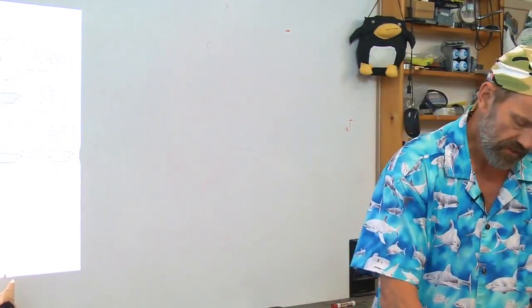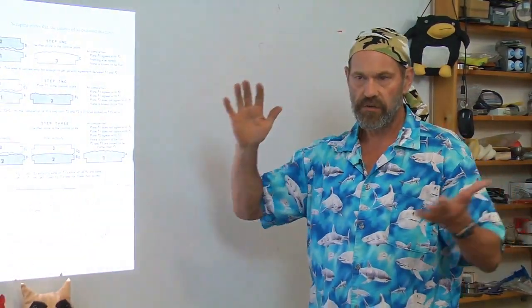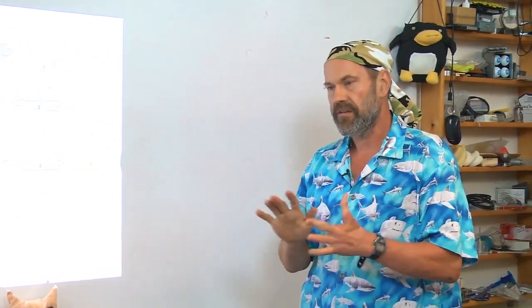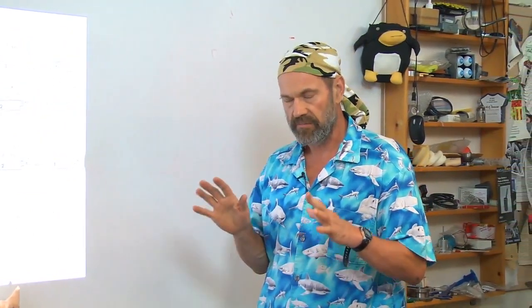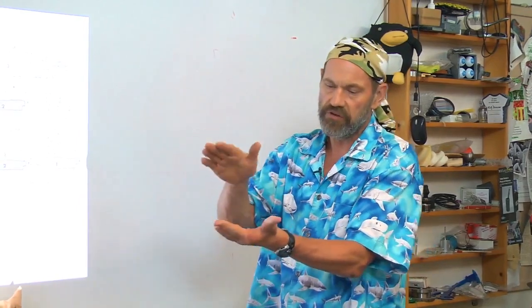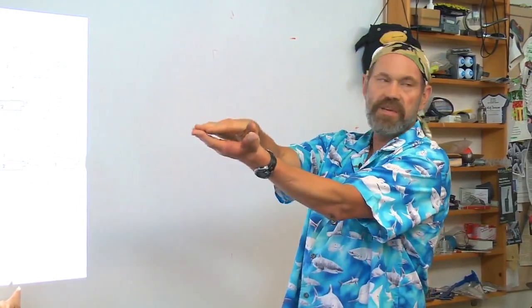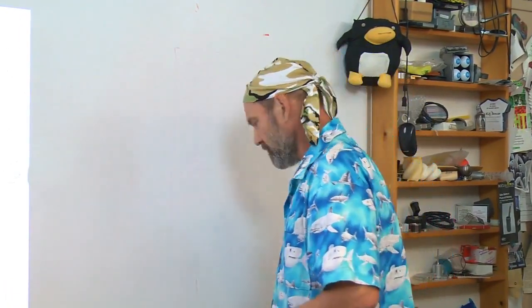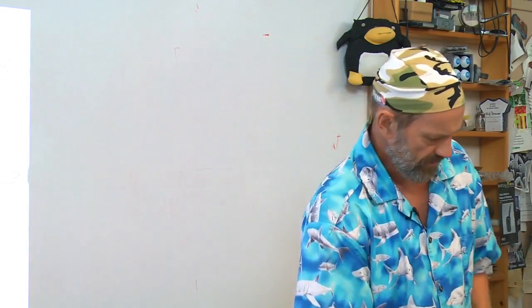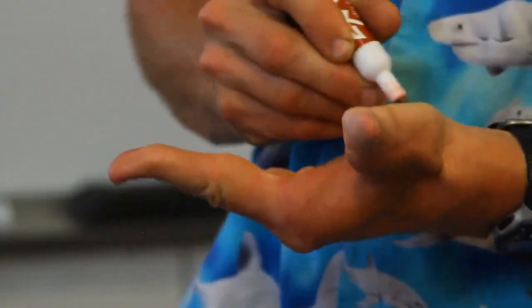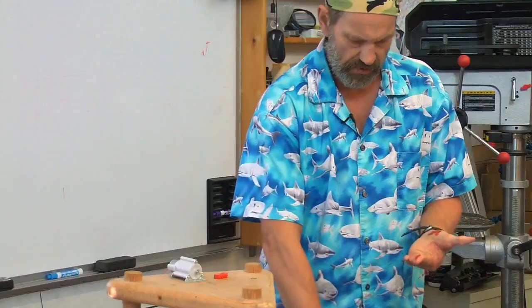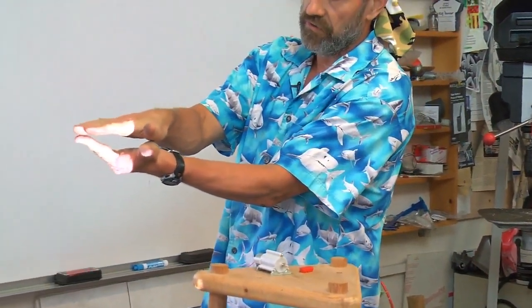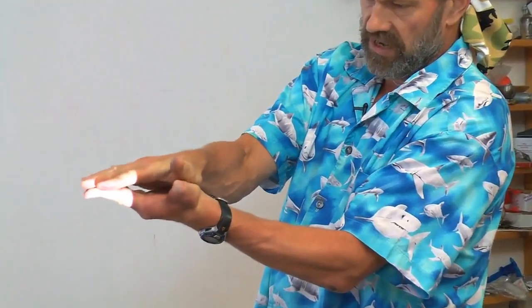Indeed, one of the ultimate forms of elastic averaging is scraping plates together. Large machines put together and bolted, you'll find that in the traditional ways of designing machines and manufacturing machines, you knew that when you brought the two surfaces together, there would be gaps between them. So you put a little bit of coloring on one. Let's see if I can do this real-time experiment here. So if you put coloring on one against the other, when you brought the two surfaces together and touched and pushed and get what's called rubbing a bearing,